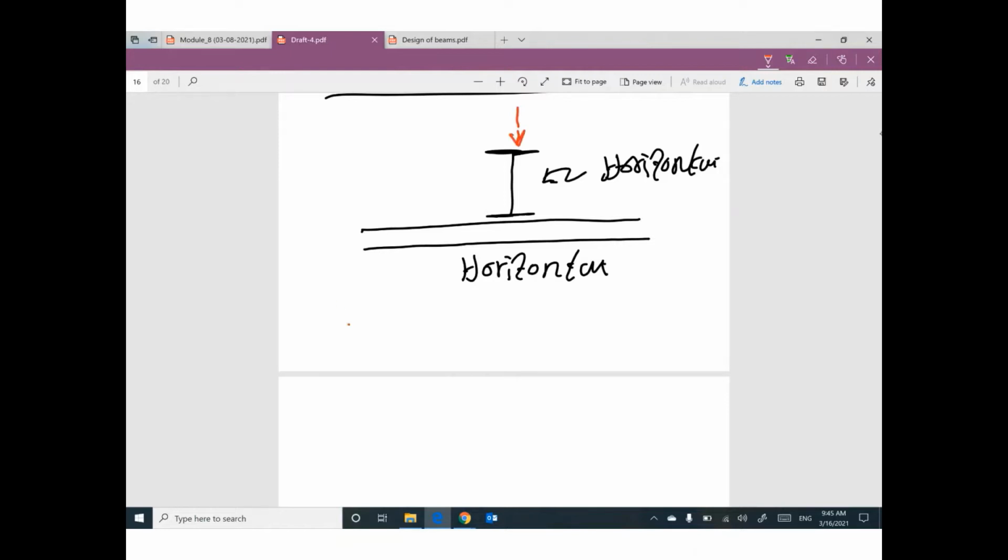So the bending moment diagram on this beam will be WL squared divided by 8, for example. This moment will be Mx, or M ultimate x, because here is the x-axis for this beam. This M ultimate x must be smaller than or equal to phi Mn. This Mn will be Mnx.